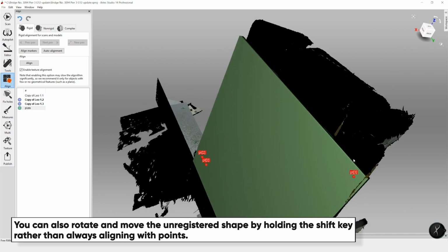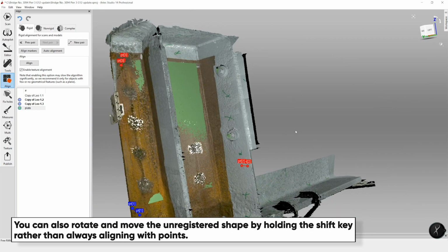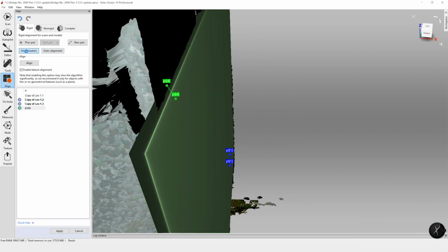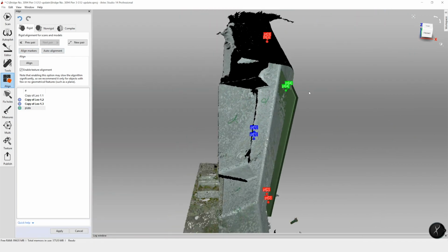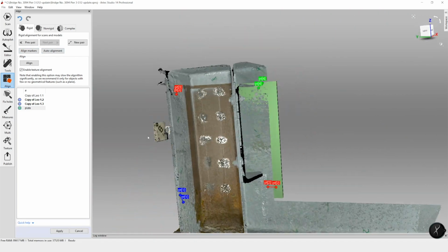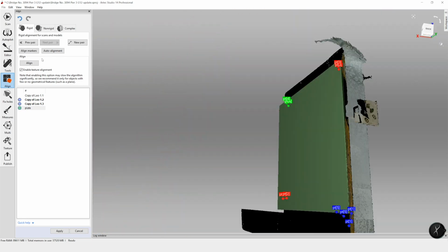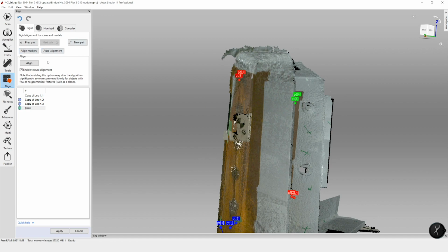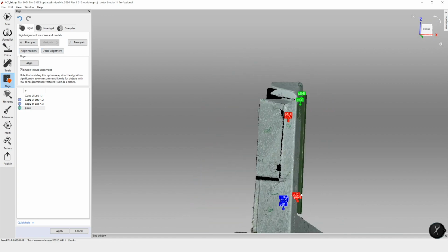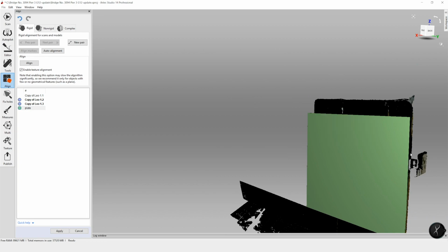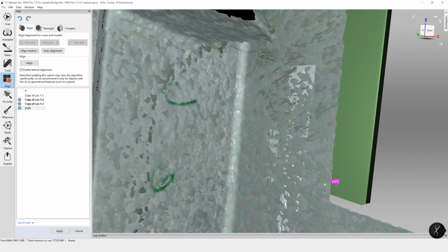So this picking points is the same way done in the previous video, and what you want to do is just get it so that the face of the plate is lining up with the face of your beam. For the plate, I brought in an OBJ file that I generated in SketchUp, but this can be a variety of file types generated in a variety of platforms. Really, whatever works best for you to bring in the 3D model, you can use that.